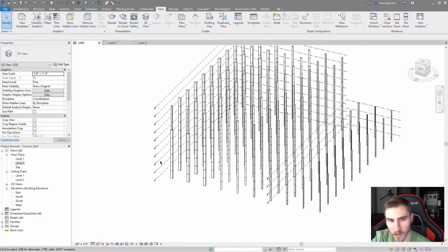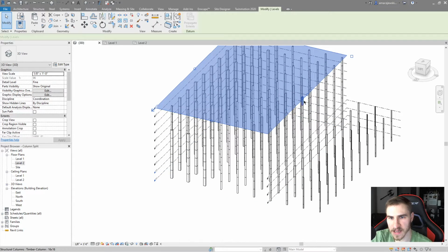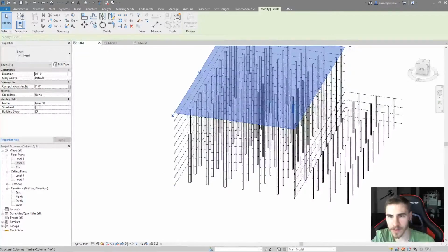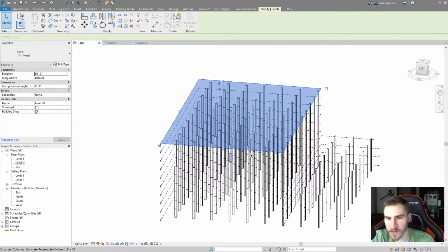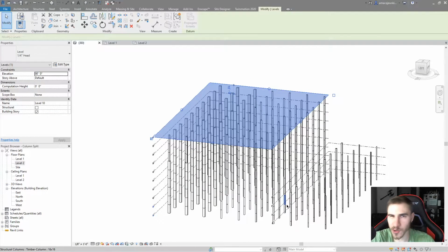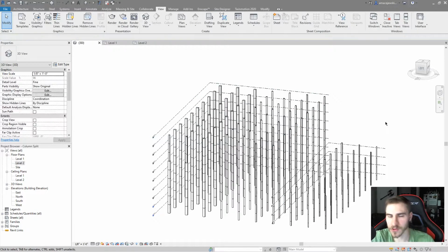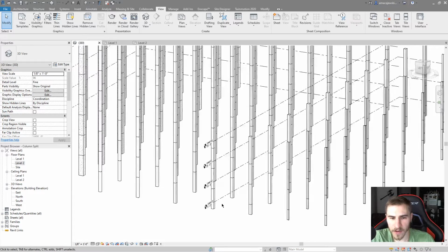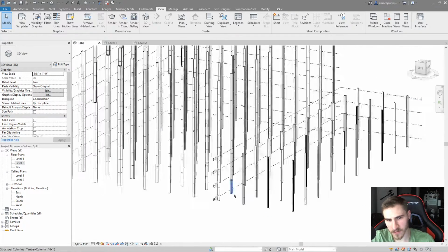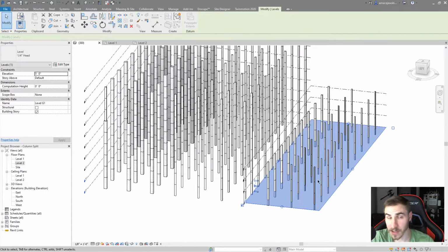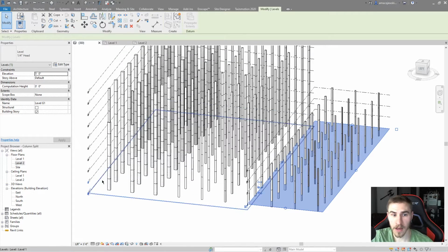And so I have all of these levels placed, and it's covering the extents of this portion of the building. You can imagine that this is like an office, and then I've got a garage, which is why I've got two separate levels or two separate areas, two different structures, whatever. And you can see over here, I've got these garage levels, and these garage levels are specifically only covering the garage. So the idea is if I cut through just the office or this portion of the building, I wouldn't see a garage level because maybe it wouldn't matter.